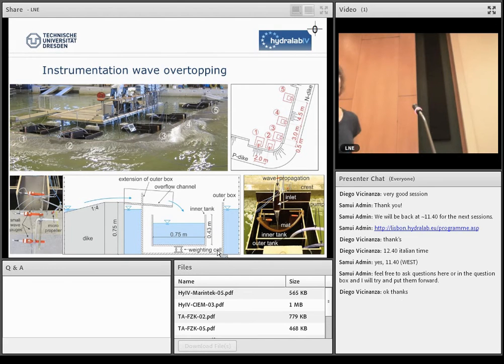and we had differences in the width of the incoming channel. So here at the P dike it was 10 centimeters wide, and at the N dike it was 30 centimeters wide, because we expected more overtopping at the N dike than at the P dike. And at each inflow channel, the flow characteristics were measured with these small wave gauges, and